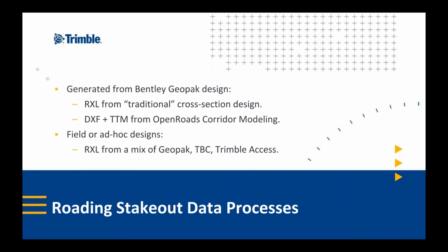So the typical processes that we use at WYDOT for generating road stakeout data: we use Bentley GEOPAK as our software at WYDOT, currently on Select Series 4. We have two different design methodologies right now that we use. One is our traditional cross-section based design. We still have a number of projects using that design, but we have also been moving over into OpenRoads corridor modeling. This year we've been starting to kick out more of our new projects designed in that fashion.